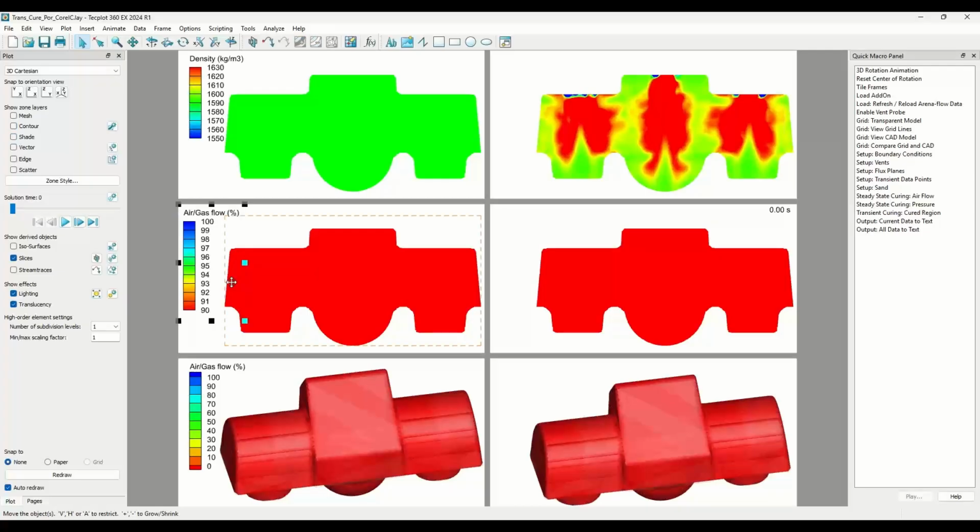In the center images, what I've done is I have reduced the scale to highlight the differences between areas cured out fully and areas that potentially will cure out when the core sits on the shelf. So there's obviously an amount of residual curing, but the 4 top views are cross sections right across the center of the blow tubes.